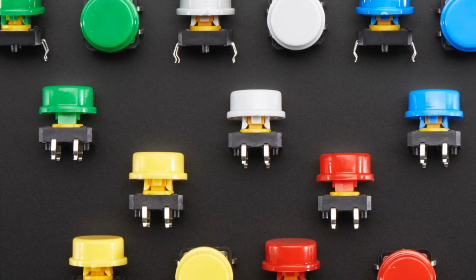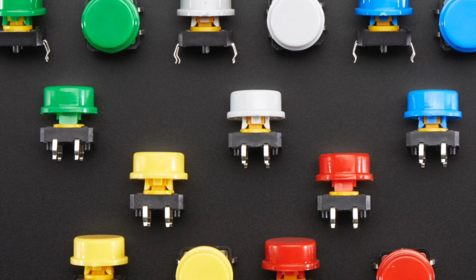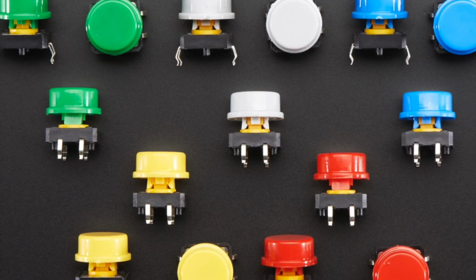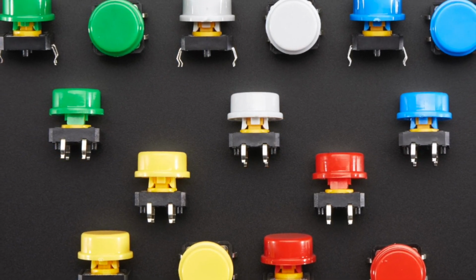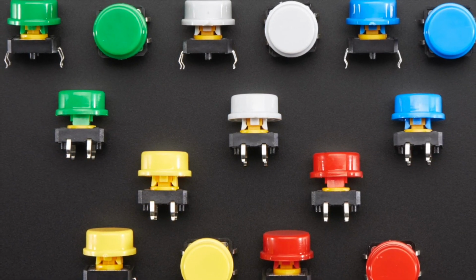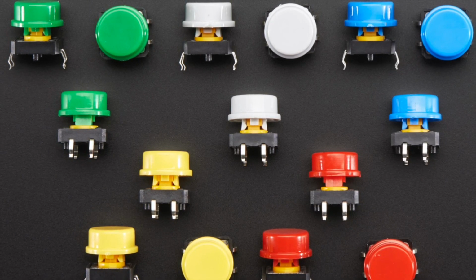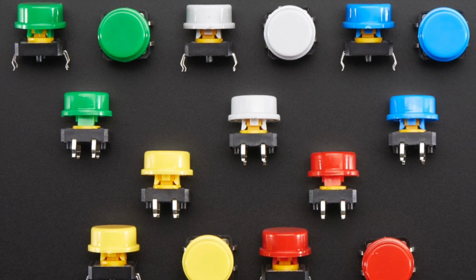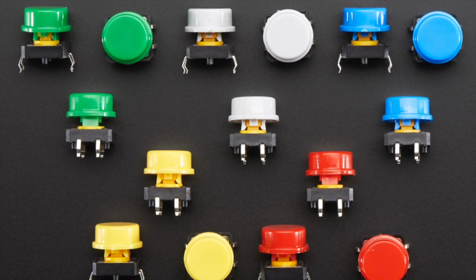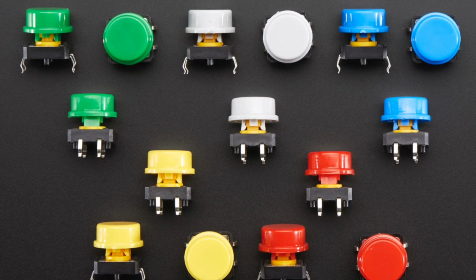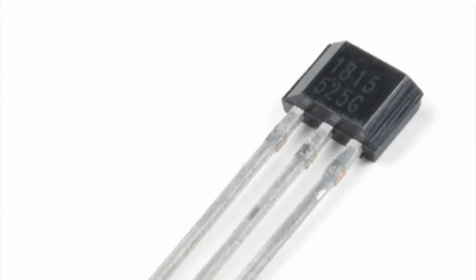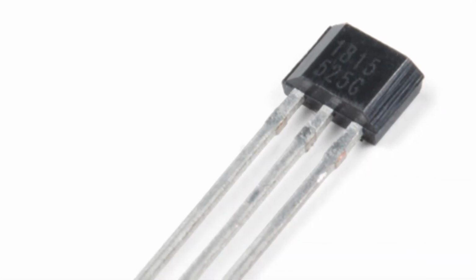I like arcade buttons for their familiarity, longevity, and ease of installation and wiring. Adafruit has some that even come with controllable LEDs. Buttons are incredibly easy to read. The pin connected to them is either digital high or digital low, depending on whether the button is pressed. You can experiment with this using the onboard buttons of the Circuit Playground, but if you want a fancier button, consider going off-board.